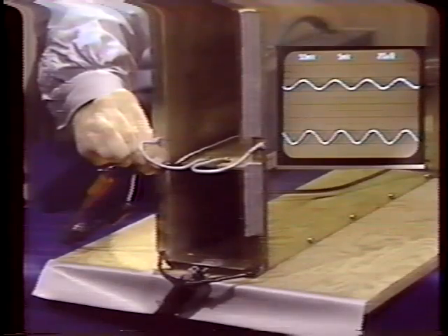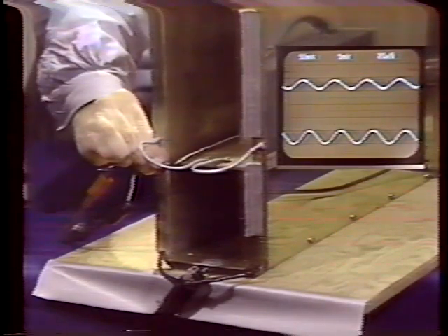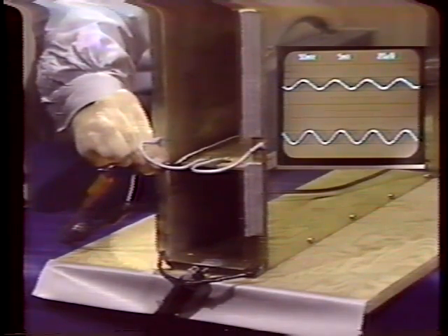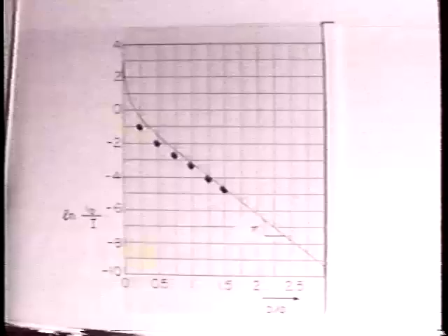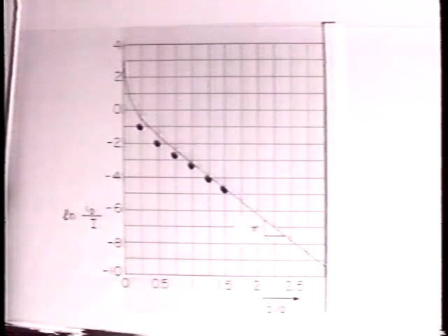Under these same conditions, the upper electrode terminal voltage was 8.2 millivolts peak, about a factor of 7 larger. This data point and others we've taken using the flux loop rather than the upper electrode terminal voltage not only have the predicted dependence on electrode spacing, but more nearly the predicted absolute magnitude as well.